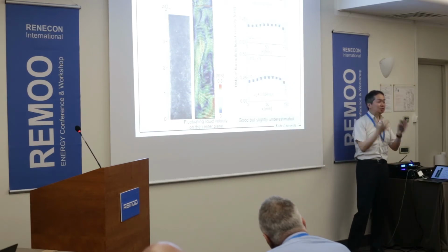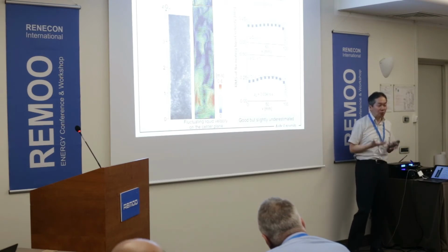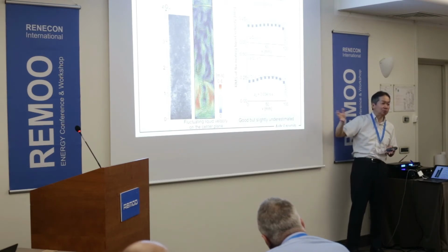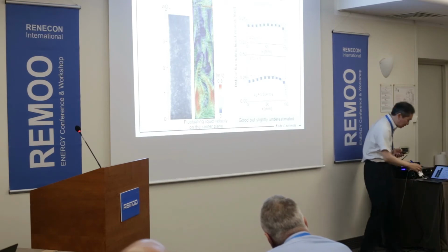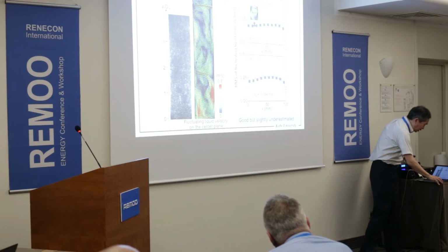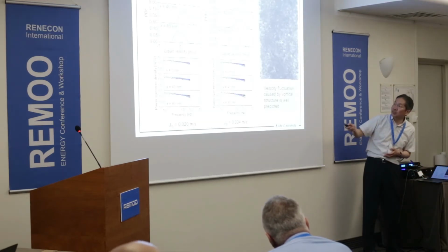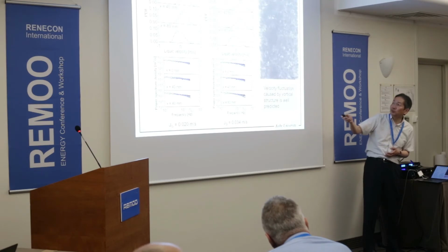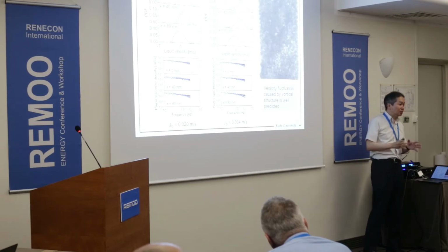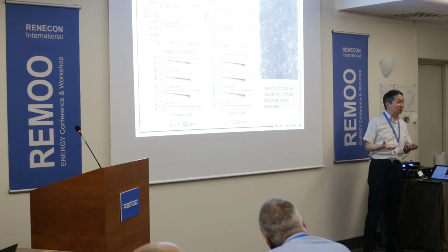So with the experimental data, we can say that even without any turbulence model, we can obtain very good prediction for a complicated system like this. And without that, we cannot say anything about it. Anyway, I'll skip every detail, but for the PDF also, we can obtain very nice agreement for every point like this. So we can also predict velocity fluctuation using the available models.